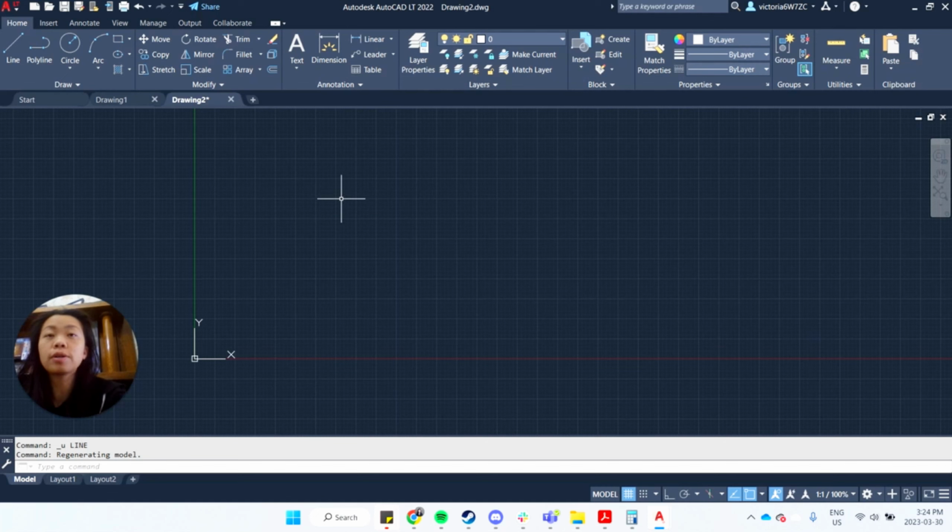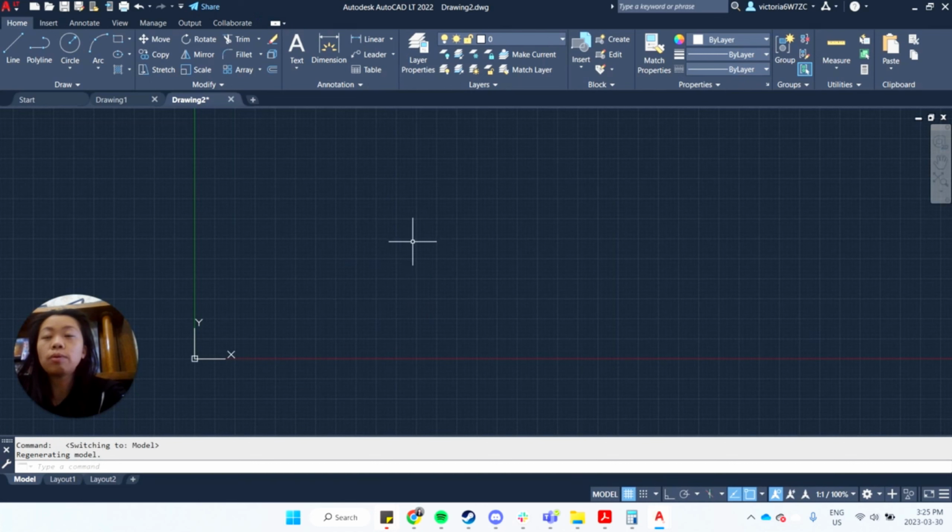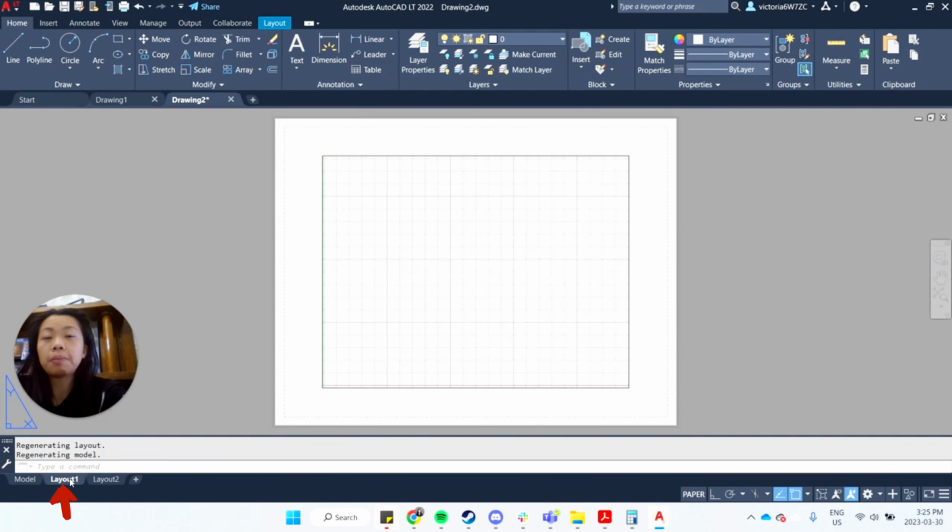And then out of that, you can produce various types of drawings. So that's where you develop and go into paper space. The default paper space, they call it Layout 1, Layout 2. Essentially in model space, you always want to model 1-to-1, right? Don't do any scaling there. Do the scaling in your paper space.